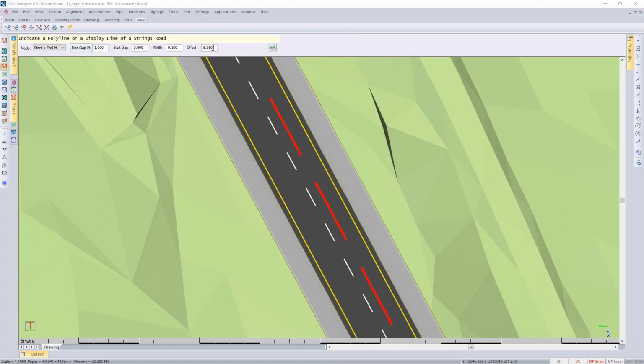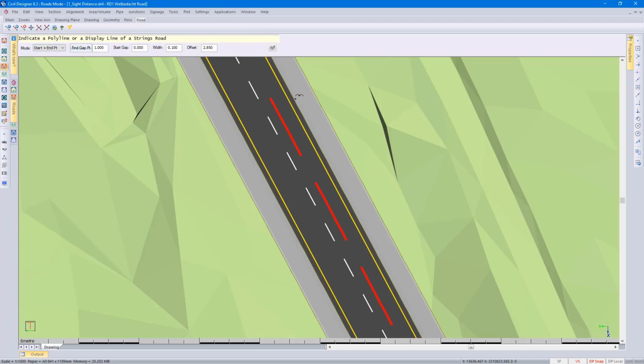Go and specify. Now, I've beforehand measured the offset. Also important in this case is to specify a start and an endpoint mode. Click on the green tick. Using the road edge I pointed out in my display settings, I left click next to the road edge, specify where I want to start, and I want to start where that white line starts. So I'm then going to press J for jump and enter. As I move my cursor, you can see that line being drawn for me. Pressing W on my keyboard and zooming out.